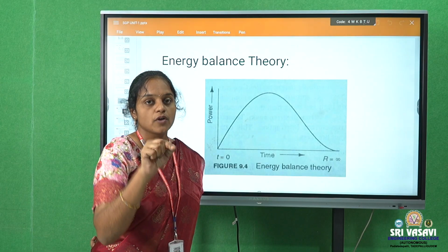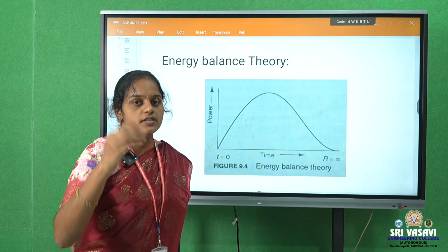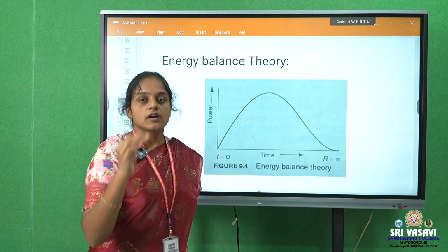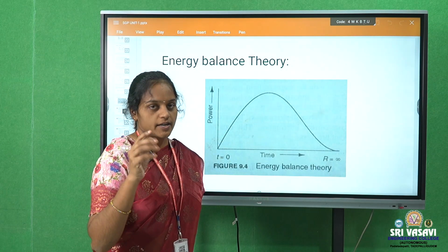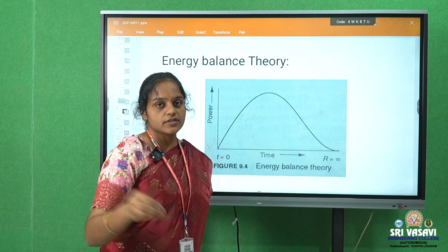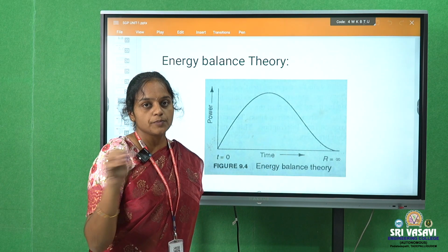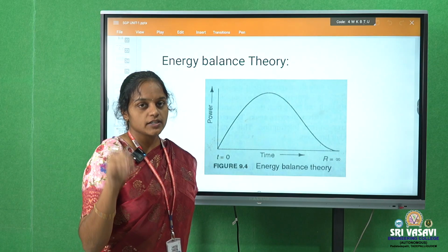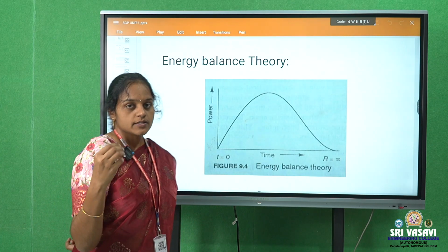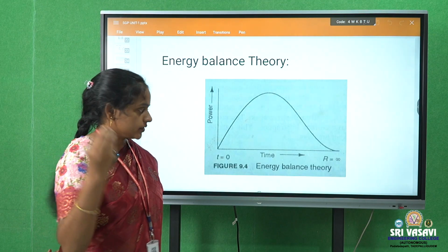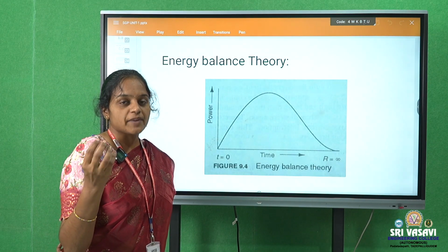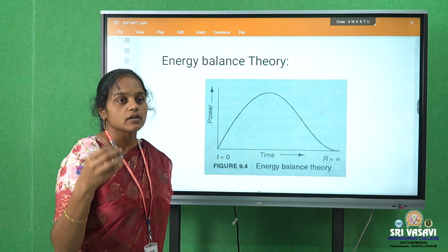But at the time of the current zero instant, resistance is infinity, because we have to maintain the resistance low at that time. So to reduce the resistance between the two contacts, which is present in the arc, we have to produce some dielectric material, like by pumping pressurized oil or by pumping cool air.